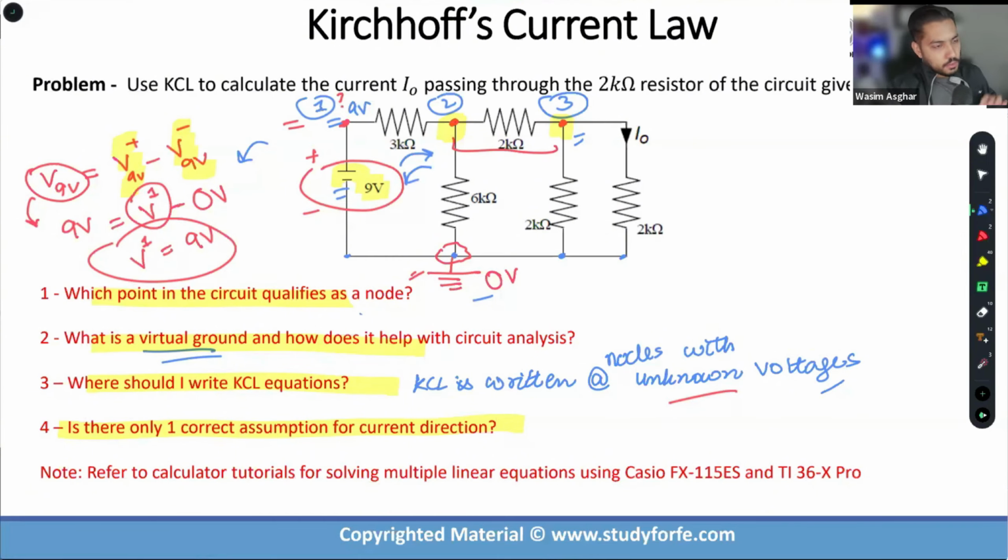In fact, the way that I am going to solve this circuit as a homework assignment, I recommend you actually flip all the current directions, solve the circuit yourself, and you are going to see that you still get the right answers. Maybe in some cases, you will have a negative sign associated with the current, which basically means that you simply have to do one step adjustment. The negative sign indicates that the actual direction of current is opposite.